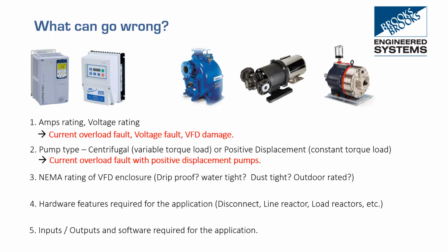Another thing to consider, we talked about how positive displacement pumps have higher requirements for VFDs. So when we're selecting a VFD, we should again check with our supplier that the amp rating they're giving us is the constant torque or the heavy duty amp rating for a positive displacement pump.